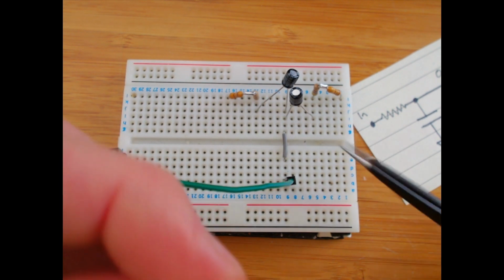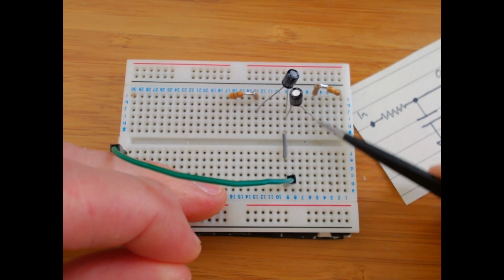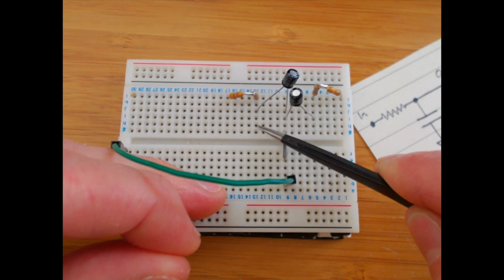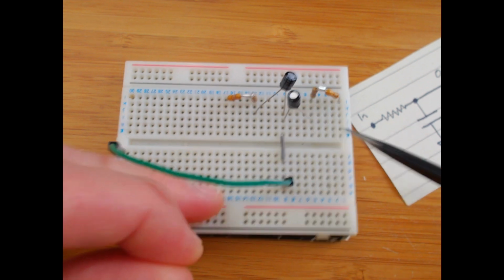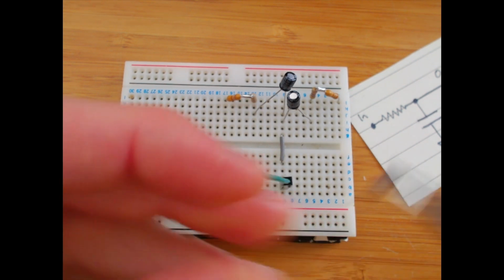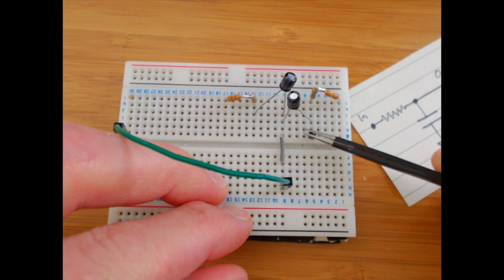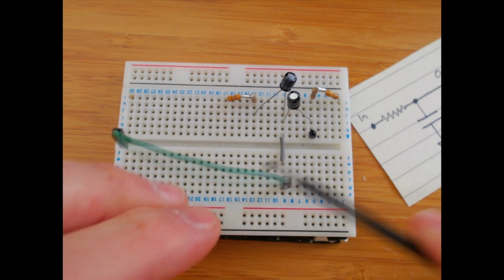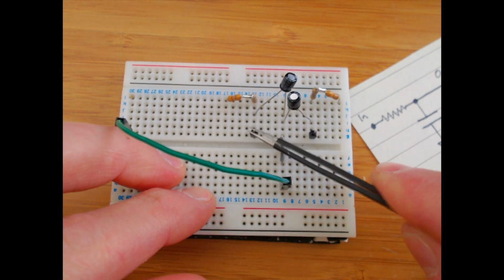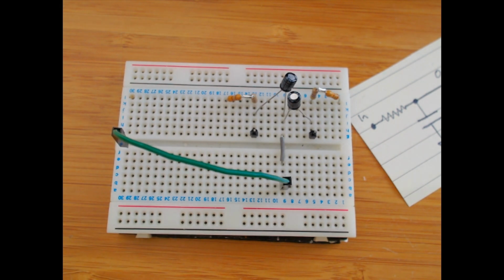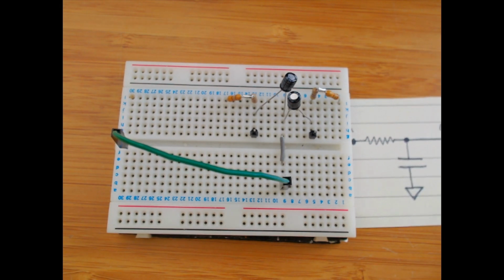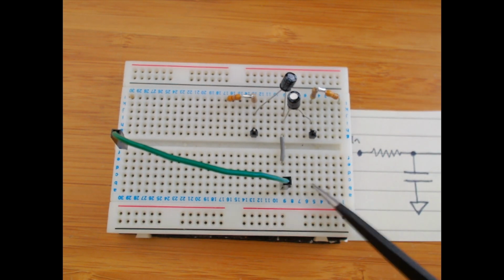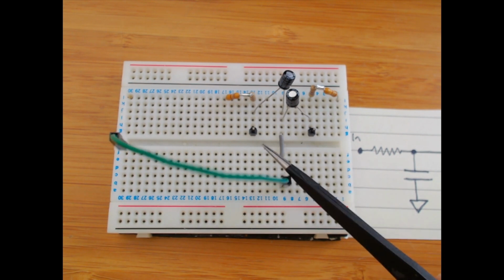And then what I'm going to do to take the signal, so the signal actually comes out at this point and at this point, right? These are where the resistor and the capacitor meet. So I'm going to stick just a little pin header in there at this point, and then we can clip the scope to these points. All right, that's it. That's the filter built. It looks exactly like the schematic, and now we can pump in our PWM and observe the signals here.